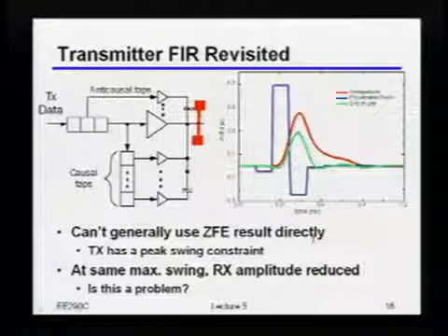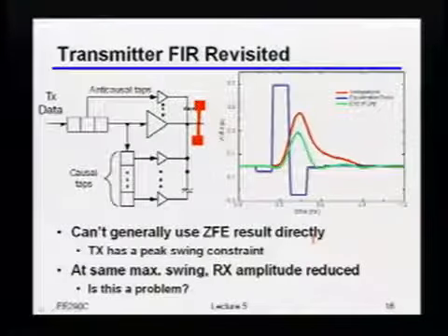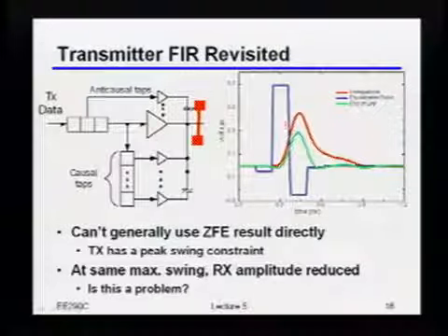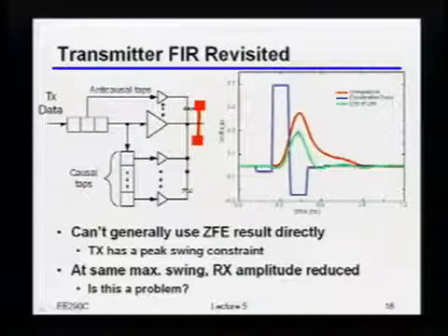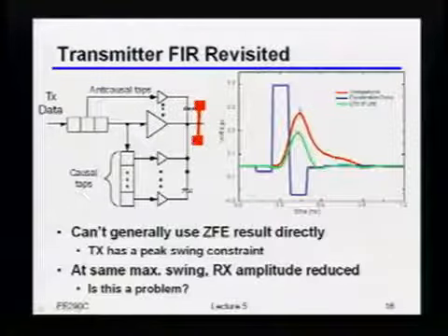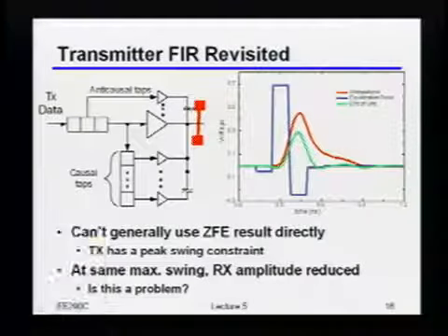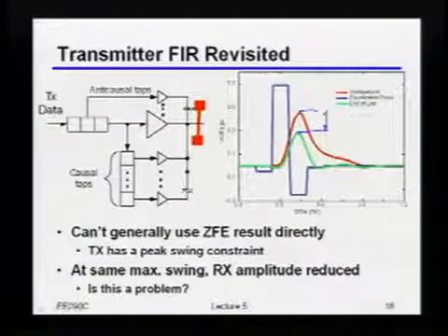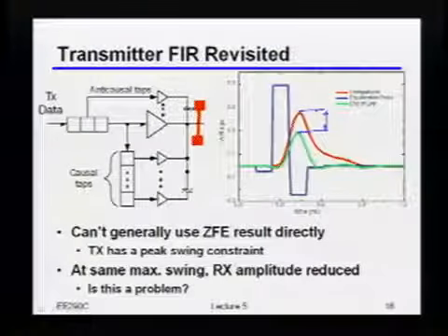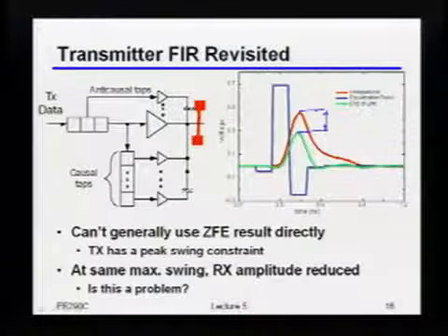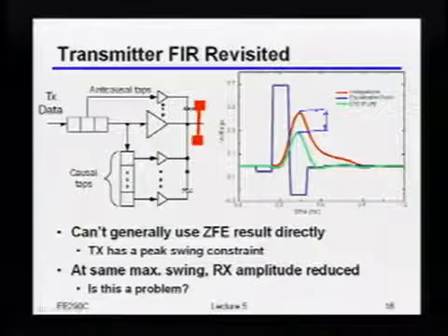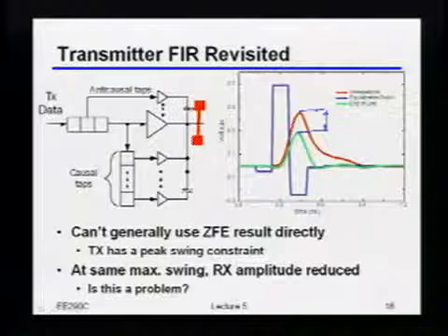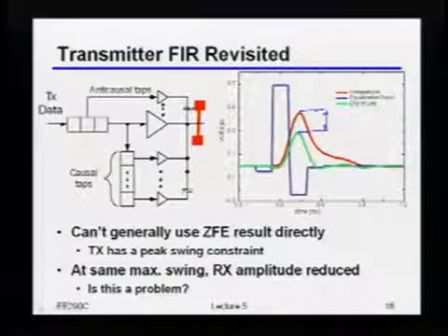In particular, looking at this black waveform, which was my transmitted pre-emphasized waveform, if you compare the magnitude of this green pulse to that red pulse, which was the unequalized one, notice that after equalization, the amplitude I get is smaller. Because if I kept the peaks the same as I used to have, then in order to do that equalization, my only choice is to make things smaller.